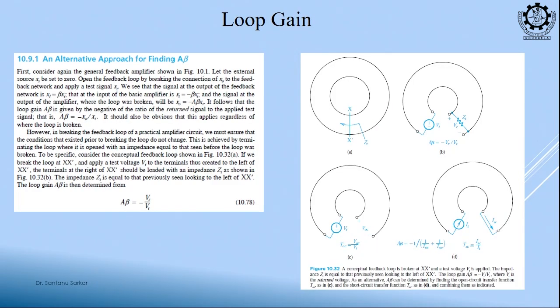So, this is how we find the loop gain. Okay. When a circuit is given, if you want to find the loop gain, you have to break the loop. If a continuous connection is given, you can't calculate the loop gain. Then what can you do? You can break a portion and put a source and then find the output. As if this is a loop, right. So, we do not know where to start. So, what we are doing? We are breaking at this point, we are adding a voltage source V and we are finding the output voltage V0.